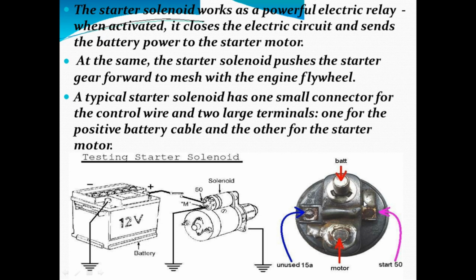So when required, the gear should be pushed towards the flywheel, and when the function is over, that means when the engine gets started, the gear should come back to its original position. For that purpose, we are using this starter solenoid.